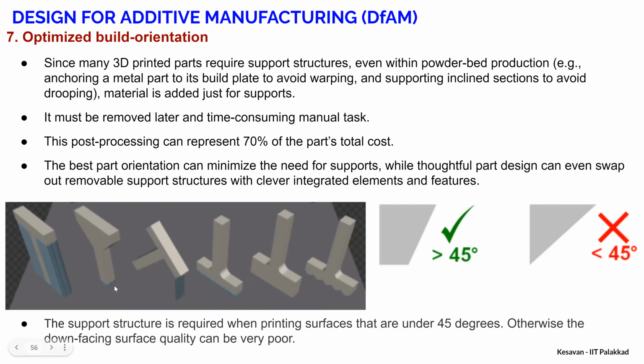Among all these options, you should avoid the first orientation, which requires a lot of supporting material, right? You should avoid that. The rest are okay because they are not adding too much supporting structure.